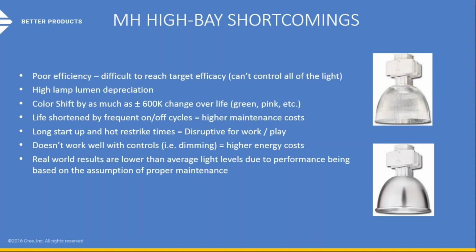Another option is the light levels themselves. So over time, as we mentioned, the lumen depreciation turns basically into a problem with light levels. When you first do your installation and you meter it, you see that you're getting 35, 45, 50 foot candles of light. Over time that actually is going to adjust pretty rapidly, and you might fall well beyond what you typically would need for the job and the performance needed. So taking that into consideration, light levels are a really key item, and again, that also reflects back to maintenance and whether you relamp earlier or later within the product family.